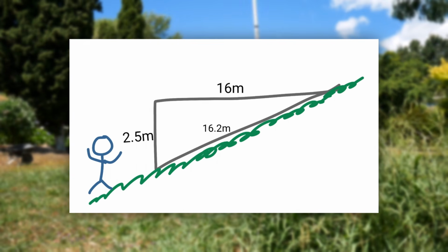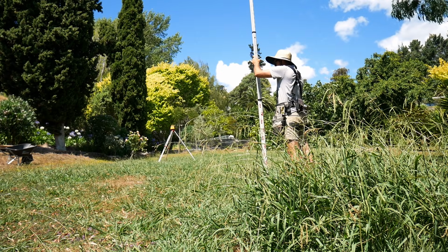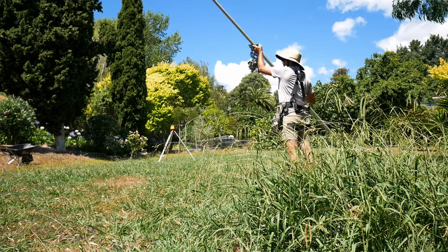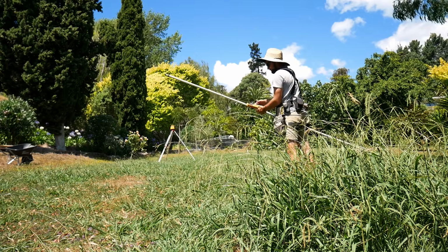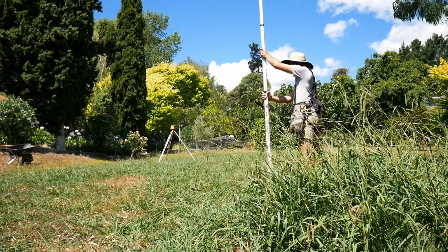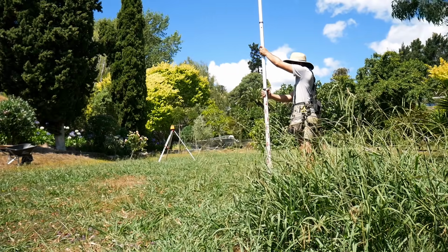At this stage, it's also important to check the accuracy of the existing heights at each corner. What these checks revealed is that if I followed the designer's intention, setting the house height 550 millimeters from the current ground level at the back corner, I'd end up with piles exceeding 3 meters at the front.